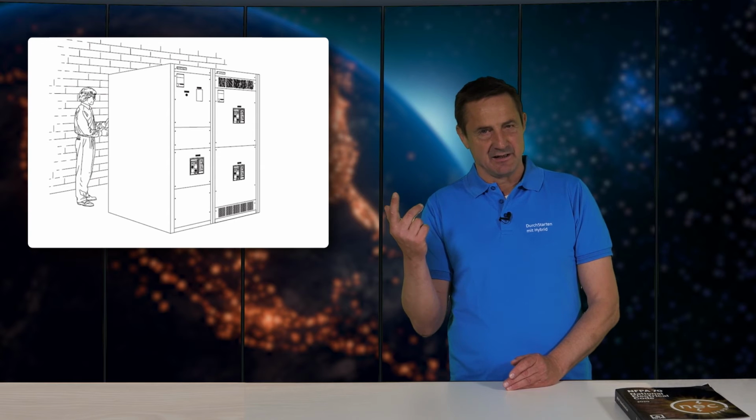To give you an idea about the electrical power distribution of a switchboard, the main overcurrent protection device in the service section is usually a circuit breaker. In case of a molded case circuit breaker, with an ampere rating between 400 and 2000 amps. In the case of an open air circuit breaker, up to 5000 amps. The maximum ampere rating of a switchboard is limited to 20,000 amps, and the maximum voltage rating is 600 volts. This is stated in the UL 891, the safety standard for switchboards.